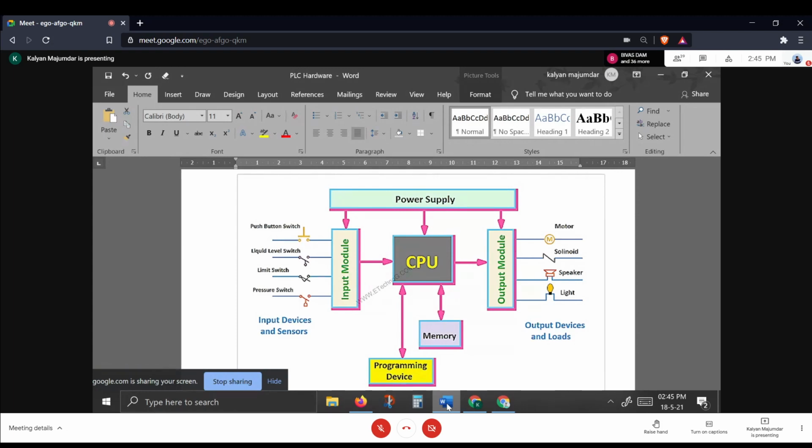You have additional components that are stored. So if one of the components is not working, you simply replace the component and the PLC is again back to normal. That way you reduce downtime. But what is important is that there should be means of clearly identifying what's wrong, and means of quickly replacing that so that downtime is reduced. That's a very important consideration when it comes to PLC hardware. We'll see how that is implemented.